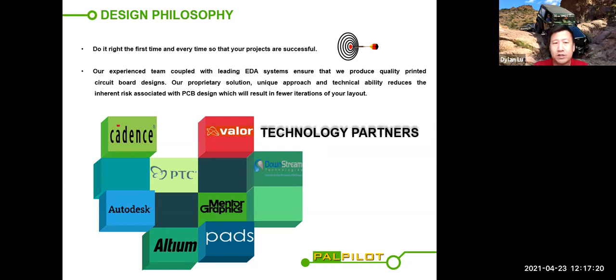But with good software like Cadence Allegro and Mentor Graphics, they have what's called Constraint Manager. It's an environment where you key in your electrical constraints and physical constraints, and then the tool will regulate the layout environment based on the rules that you enter.